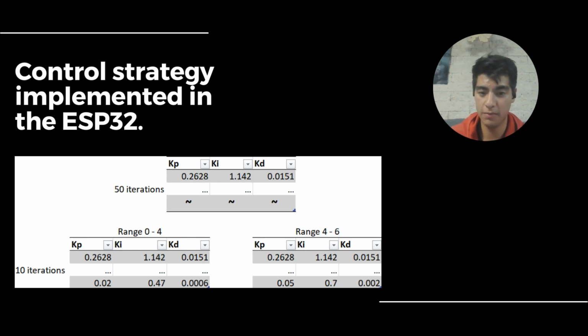When we use the control system, we notice that it works very well in the low range, but not so well in the high range. We realize that a PID type controller that works well under all conditions doesn't exist. It may work regularly, but it will only be effective under certain conditions.